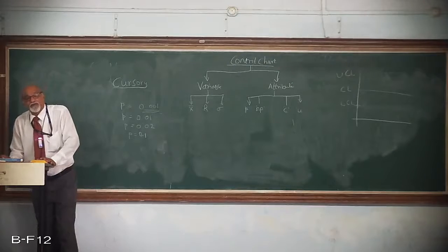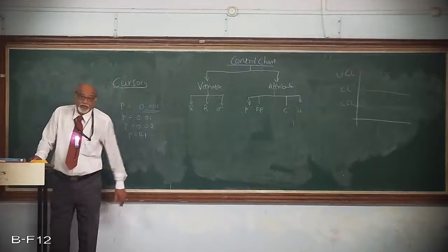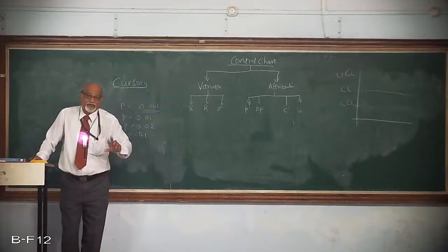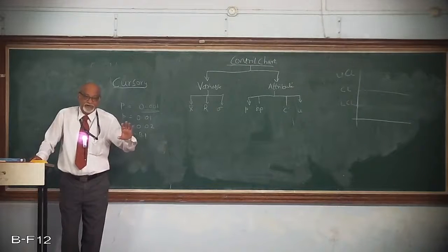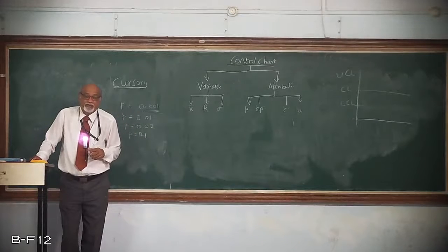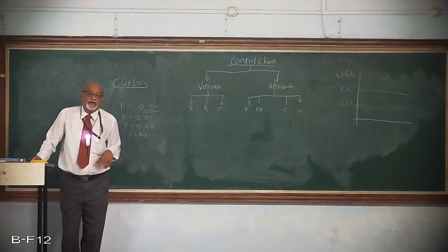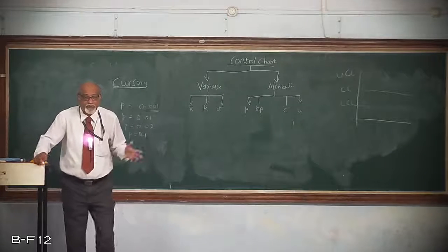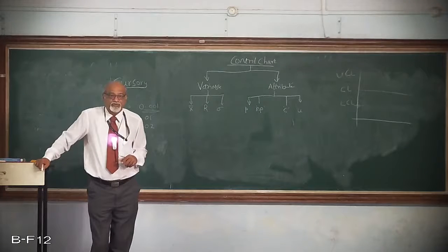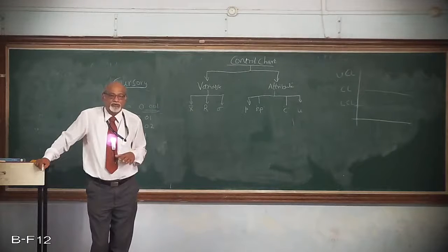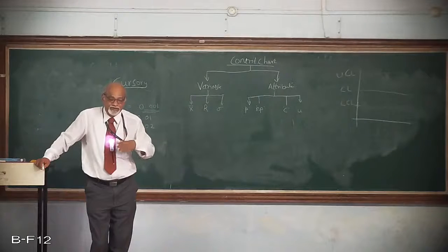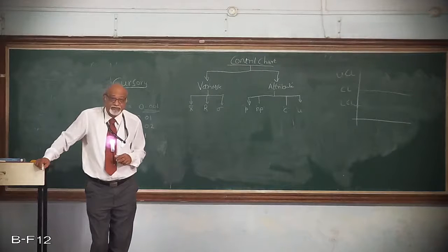Or again, out of 11 consecutive points, if more than one falls outside the central line on one side, then again we can stop. Out of 14, 2 are expected to fall outside on one of these sides, but otherwise the other things might be in a random way.